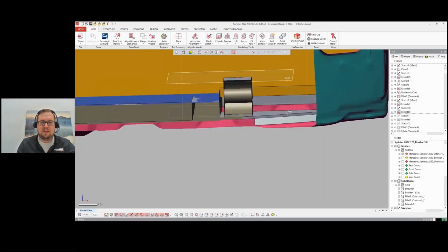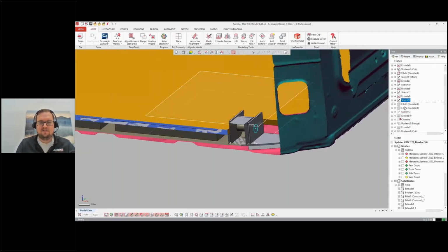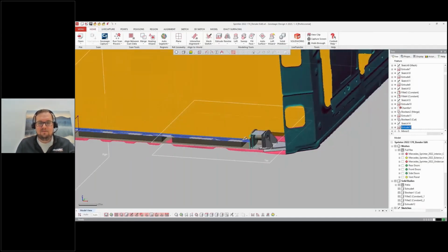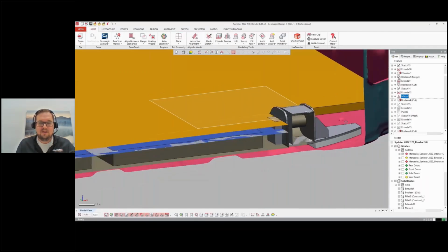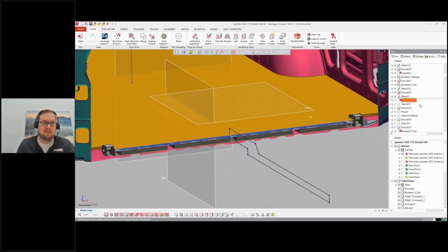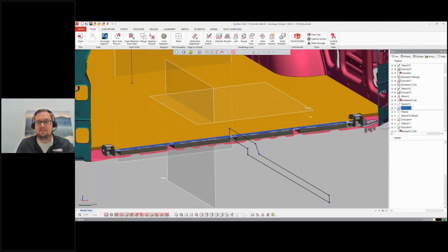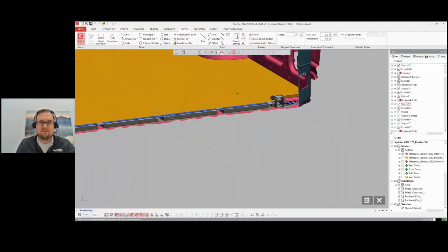Right now, I'm bringing in a steel bracket. Very simple bracket building here, just a multi-piece welded assembly. I'm grabbing some supports and extra features, and making sure I put my hole through for my pivot. But now I need to be able to clearance this, so I'm going to add a clearance for a nut or a clevis pin to go on the other side of this assembly. And as I'm doing this, I'm mirroring across to both sides. Again, we've aligned this so we can confidently mirror things across.